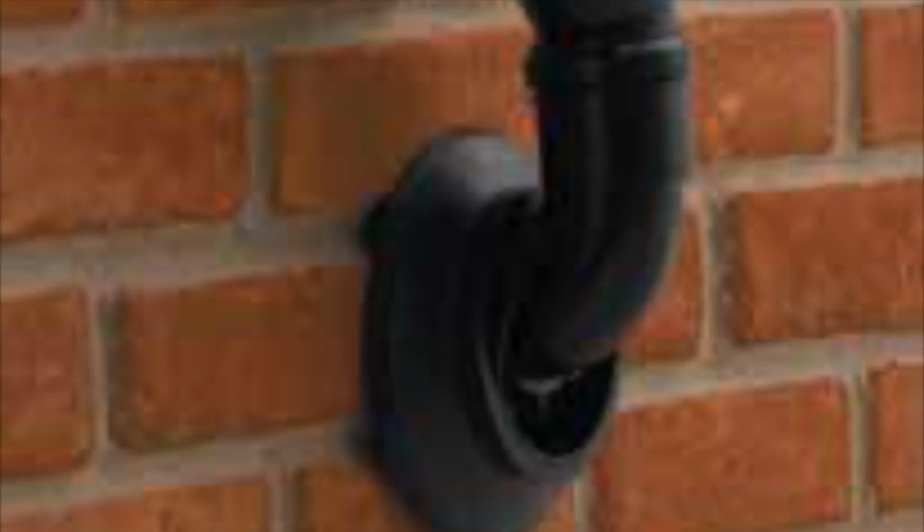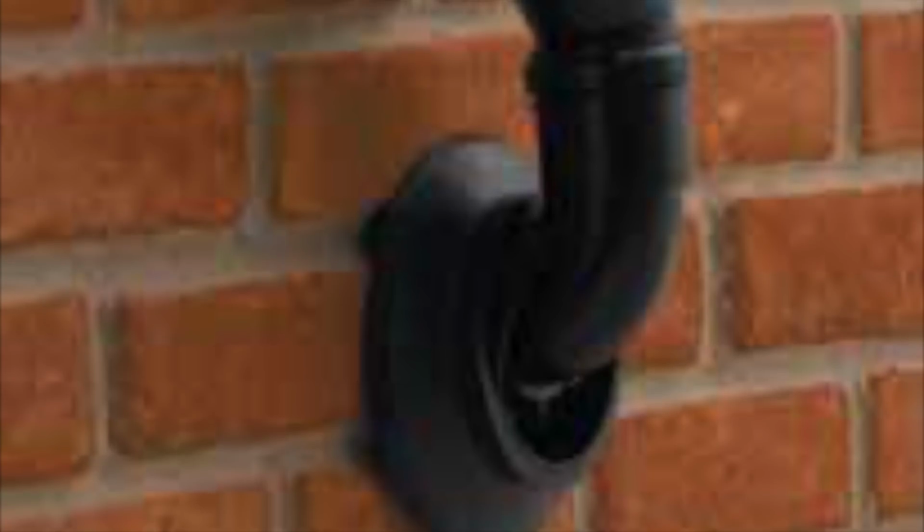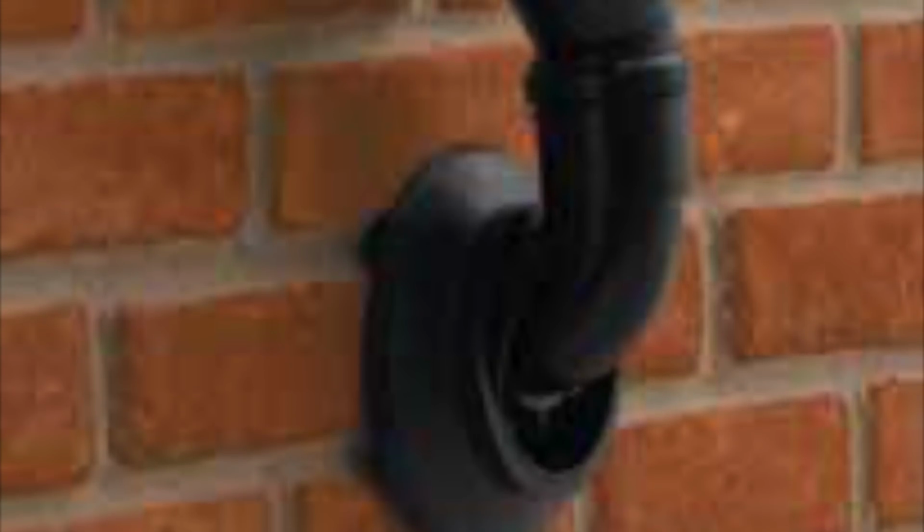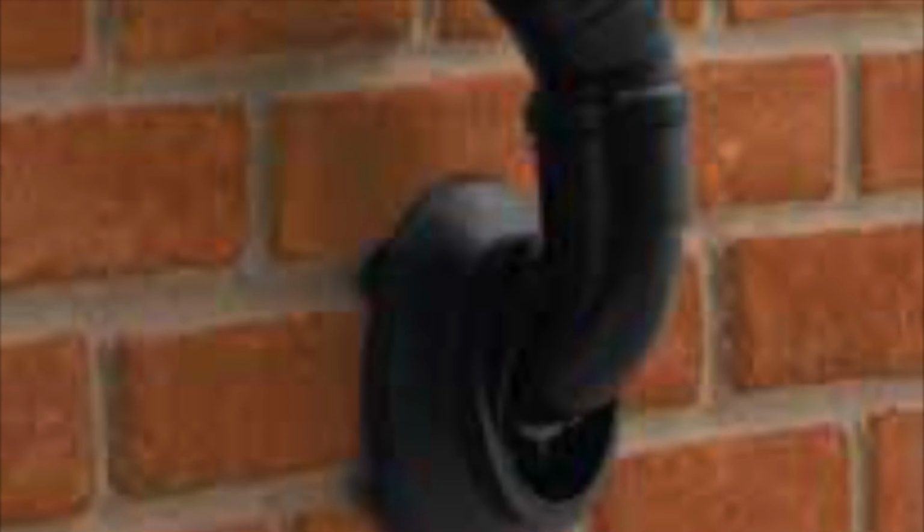So the first thing we're going to look at on the Plume Management Kit is the minimum length. The minimum length for a Plume Management Kit is 500 millimeters, and that is because if you don't do the 500 millimeters, then you're changing the categorization of the flue system. Now on this picture you can see there's an elbow straight after the flue elbow. On some manufacturers they allow this, on other manufacturers they don't. So again, you must check the manufacturer's instructions.